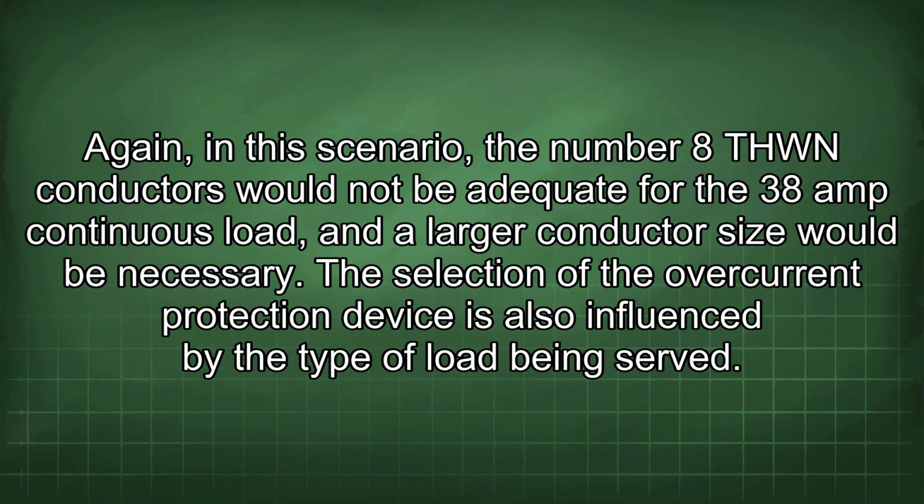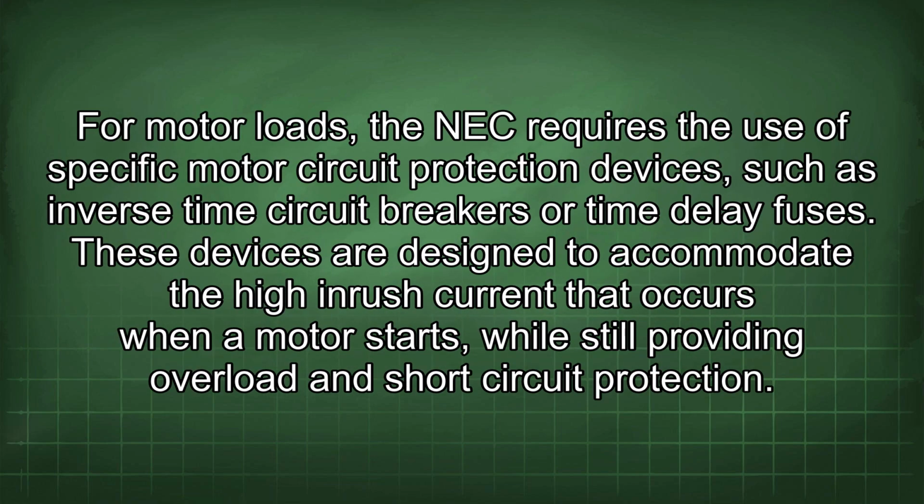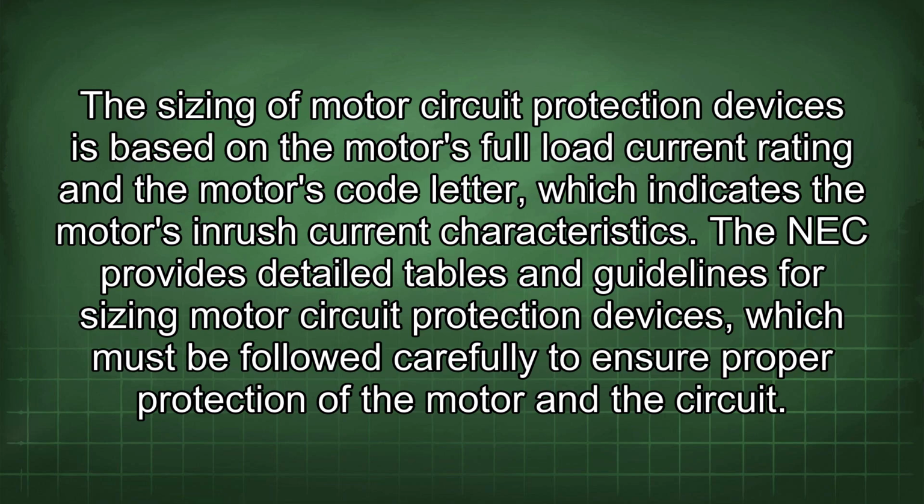The selection of the overcurrent protection device is also influenced by the type of load being served. For motor loads, the NEC requires the use of specific motor circuit protection devices such as inverse time circuit breakers or time delay fuses. These devices are designed to accommodate the high inrush current that occurs when a motor starts, while still providing overload and short circuit protection. The sizing of motor circuit protection devices is based on the motor's full load current rating and the motor's code letter, which indicates the motor's inrush current characteristics.